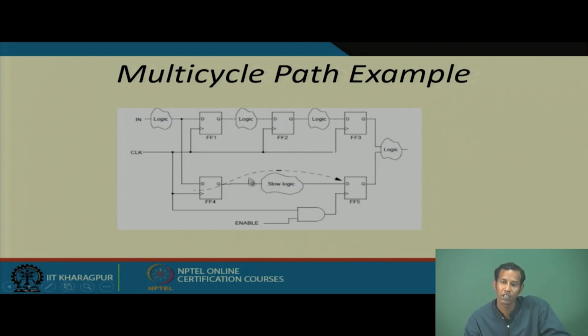So, the multiplier logic delay requirement will be much more than this full adder cell, whereas the timing requirement for the other logic is much smaller. Depending on this multiplier logic, the overall design cycle time will be much more reduced. So, if you assign that this particular logic requires multi-cycle to complete the whole operation, then this path has to be considered as a multi-cycle path. Okay.